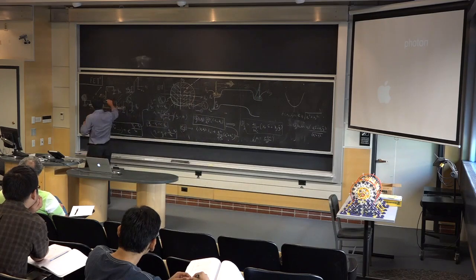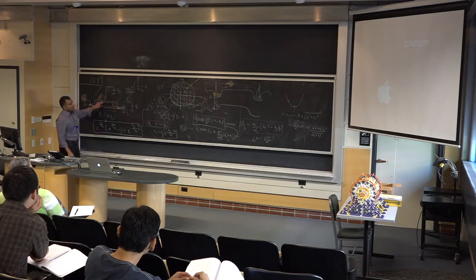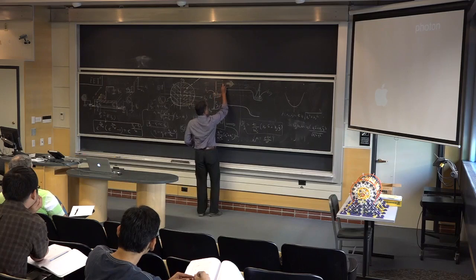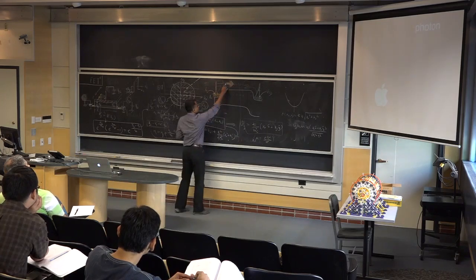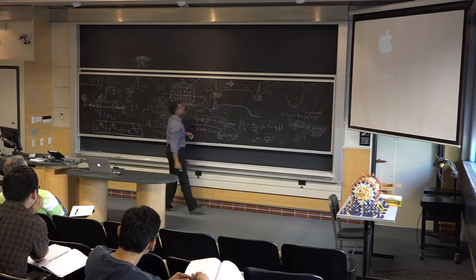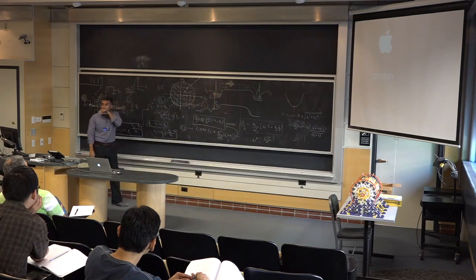If you in the gate, you mean? Yeah, if you just superimpose the parabola on the band structure. Yeah. So, right, like this. Yeah, and then if you impose the parabola at the source, then the electron intersects the parabola at 2 different points. So correct. So the kx and ky, how do they remain the same?